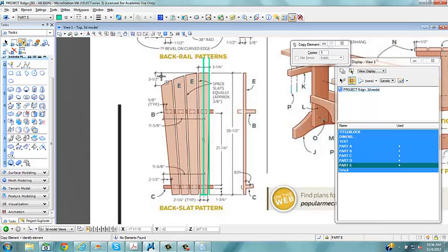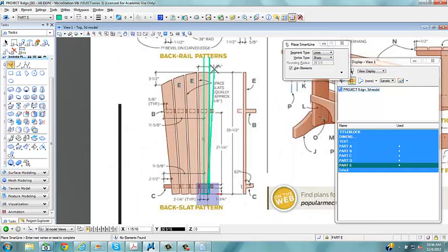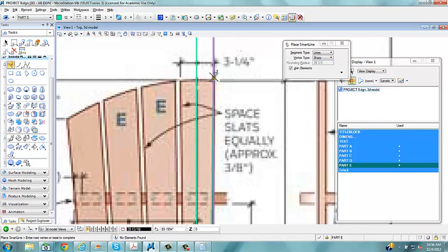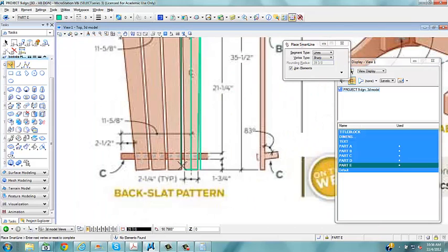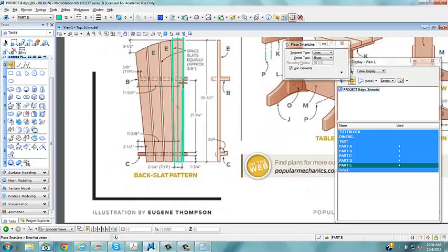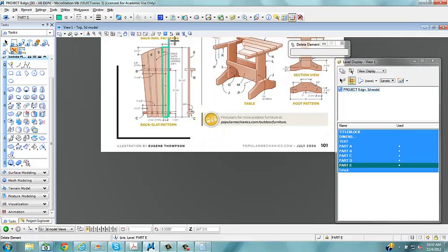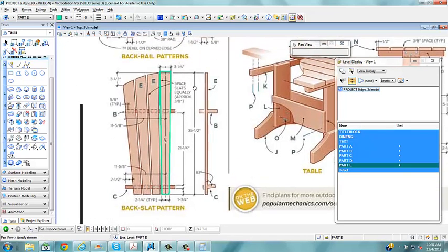I'm going to kind of eyeball this part of it anyway, because it's kind of a custom piece. And if I just spacebar N, I can put it right, let's go right to here. I'll hit V, roll it back 3.25. Oops, that's 2.25. Let's try 3.25. And we'll go all the way back down to the bottom. At least we have something that's kind of symmetrical. And we can delete this center line and that line. So we end up with this shape.